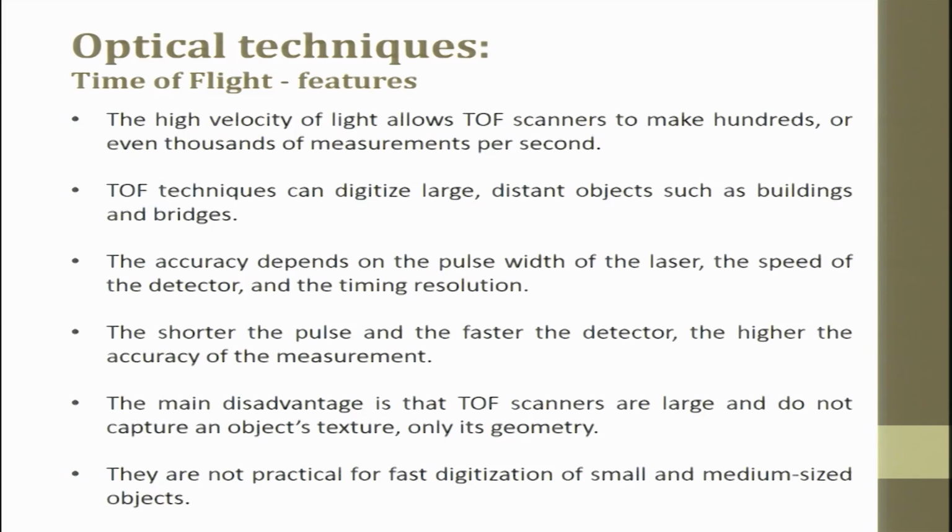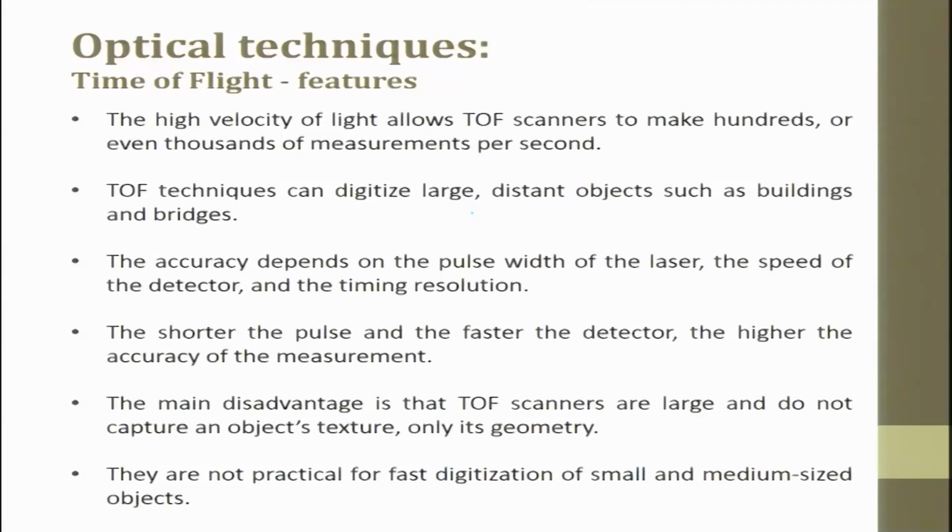The high velocity of light allows time of flight scanners to make hundreds or even thousands of measurements per second. Scan rates are very fast, and these techniques are used exhaustively. Time of flight is used in acoustic sensors, in ultrasonic sensors, and light is also used. Time of flight techniques can digitize large distant objects such as buildings and bridges. So, if you want to completely scan the Taj Mahal and do reverse engineering, we use the time of flight technique.